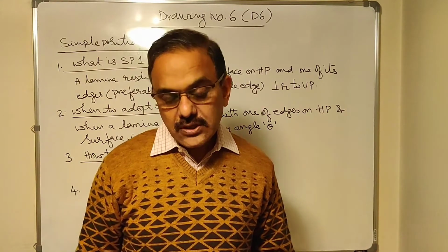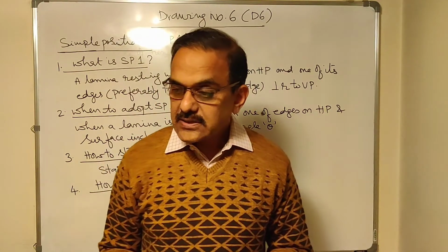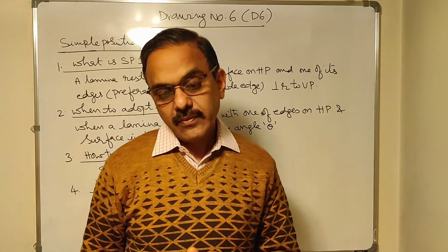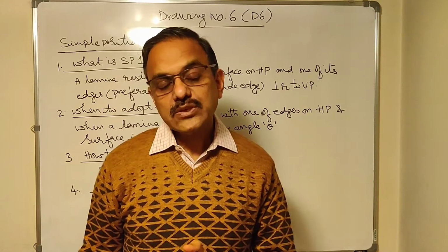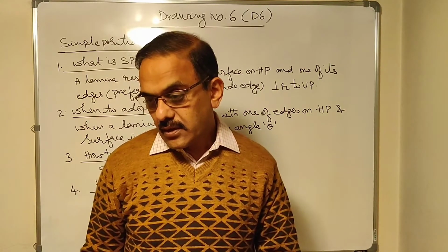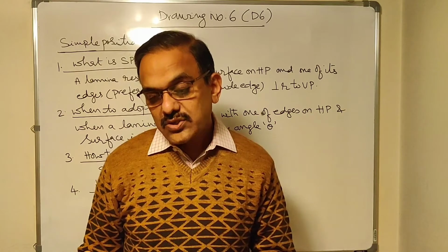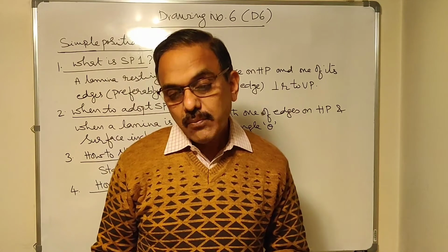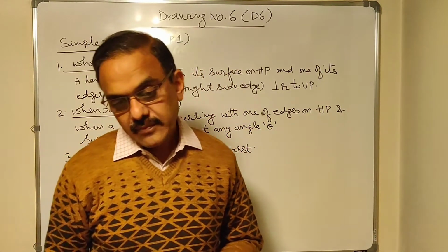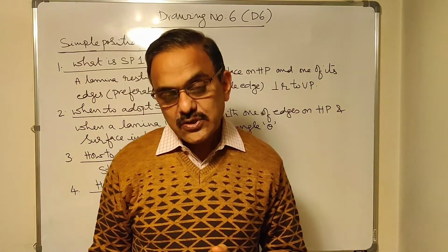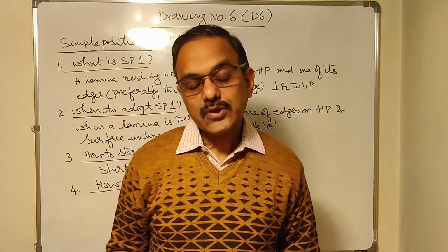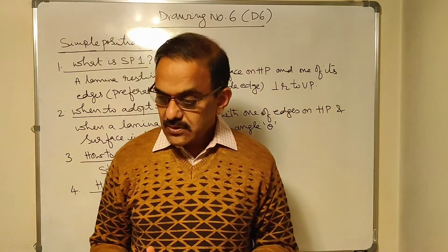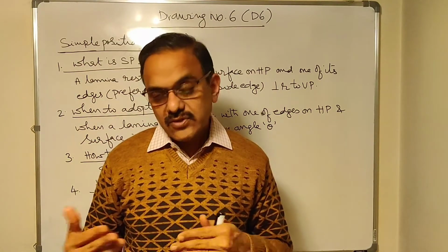Then in the remaining two steps, you will be satisfying what are called as HP condition and VP condition. Shortly we call them as HPC and VPC. You also should know which condition to satisfy first. It depends on which simple position you are adopting. So this is the knowledge which you require to solve a problem on projection of planes. So basically it is solved in three steps. The first step will be one of the simple positions.